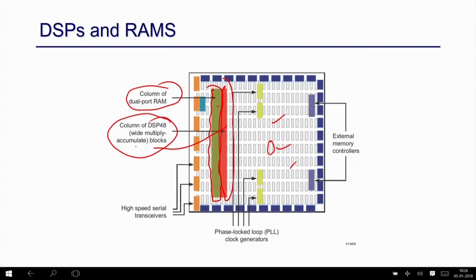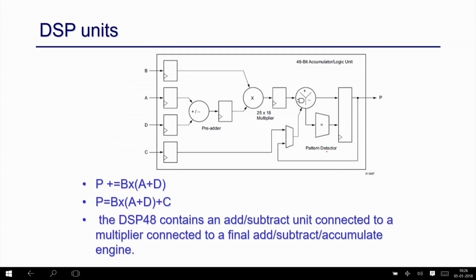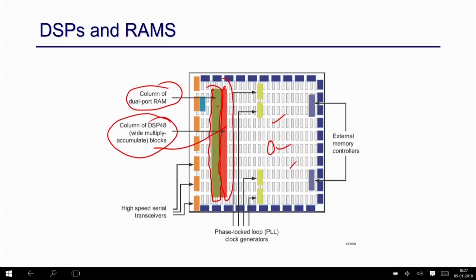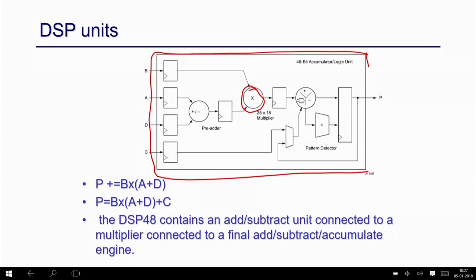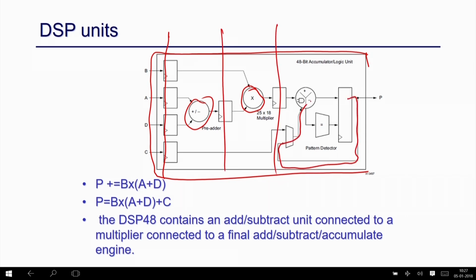So this is the overall structure. If you look into the DSP structure, the DSP is basically a very fast implementation of a multiplier. If you look closely, in the DSP block there is a multiplier, right. The primary purpose of this DSP unit is to perform multiplication in a very fast way, right. If you map a multiplier into this lookup table based design, it will be very big and it will be slow. On the other hand, the DSP is a fast implementation of a multiplier, fabricated within the FPGA board itself. But in the DSP unit, it is not only a multiplier; it can have a pre-adder, and it also has a set of latencies, right. We have 3 sets of latencies here, and this is MAC. There is a sum, S equal to S plus A, an accumulator, right. So this is what is called an accumulator.